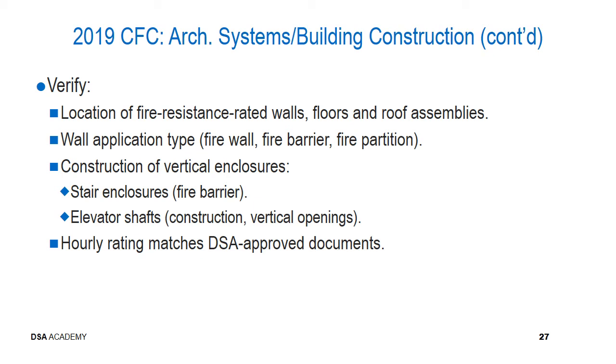At a minimum, the floor plan for each discipline, architectural, mechanical, electrical, plumbing, fire sprinkler, fire alarm, etc., must show the locations and the hourly rating of fire resistance rated walls and floor ceiling assemblies. Plans should also include construction details and the references thereto for each type of tested assembly, including the specific details where assemblies of different types or hourly ratings may intersect.